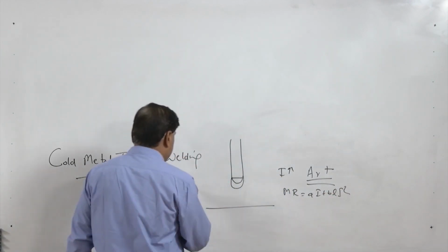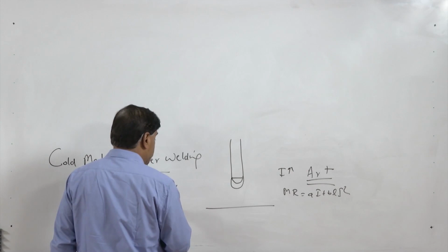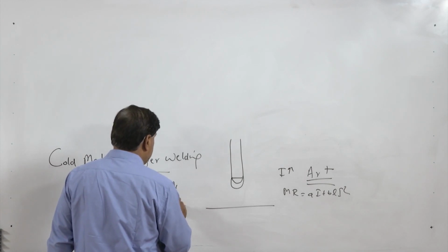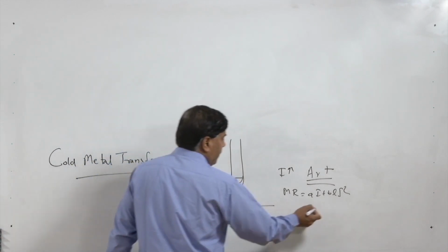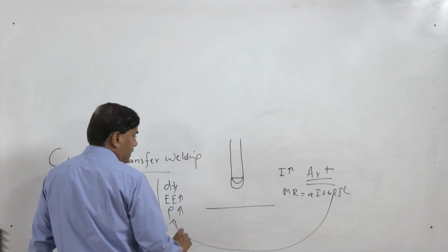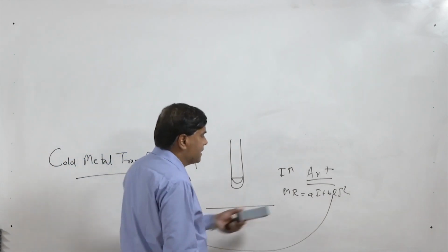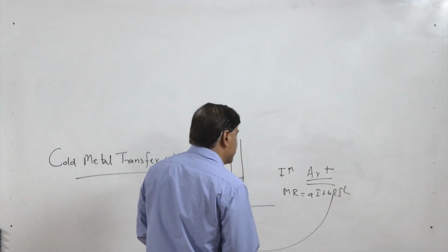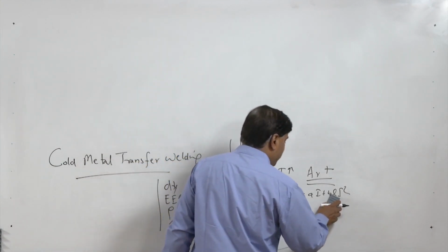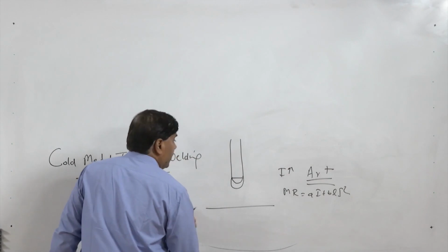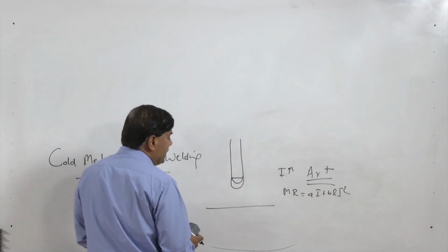So, in the case of small diameter electrodes, large electrode extension and high electrical resistivity, all these factors play a big role; in all these cases the second term plays a big role. Especially when the current is high, the melting rate is significantly influenced by the welding current, and the drops are formed very quickly at the tip.